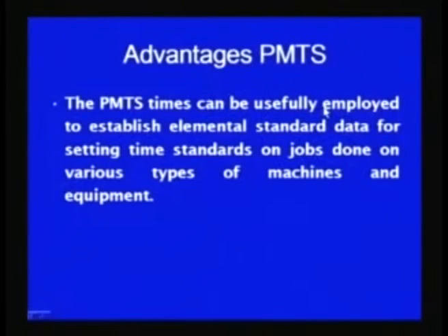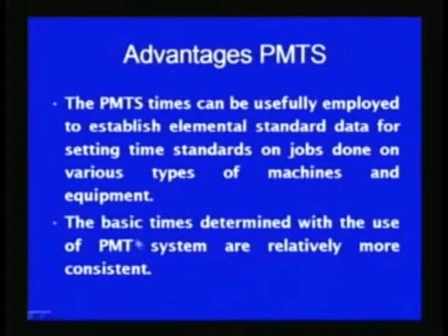PMTS can also be usefully employed to establish the elemental time data values for setting the time standard on the jobs done on various types of machines and equipment. The basic times determined with the use of the PMTS system are relatively more consistent compared to the time study ratings and the standard time set by the time study method, because the observers may rate the operator in a different way, and the operator may also work at a different pace during the actual working.